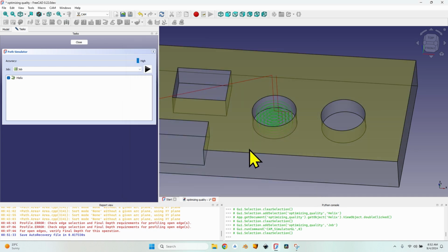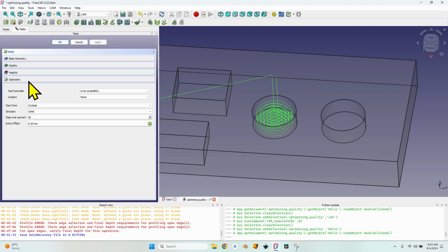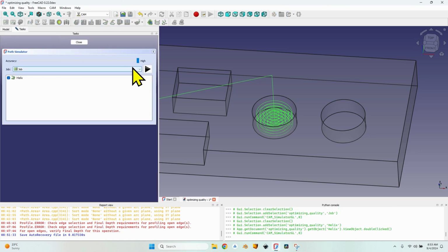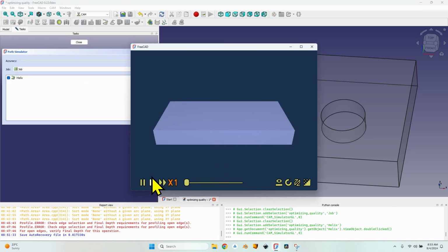When do you really need it? When I want the hole to be the exact same dimension that I have set, I will use start from the outside. Let's change the helix mode now from start from outside to start from the inside, and I will open again the simulator to explain why there is a difference between the two ways of milling the holes. As you can see, start from inside will start from the center of the hole, so I won't have that small little piece left over in the center, probably damaging the cutter in some situations.